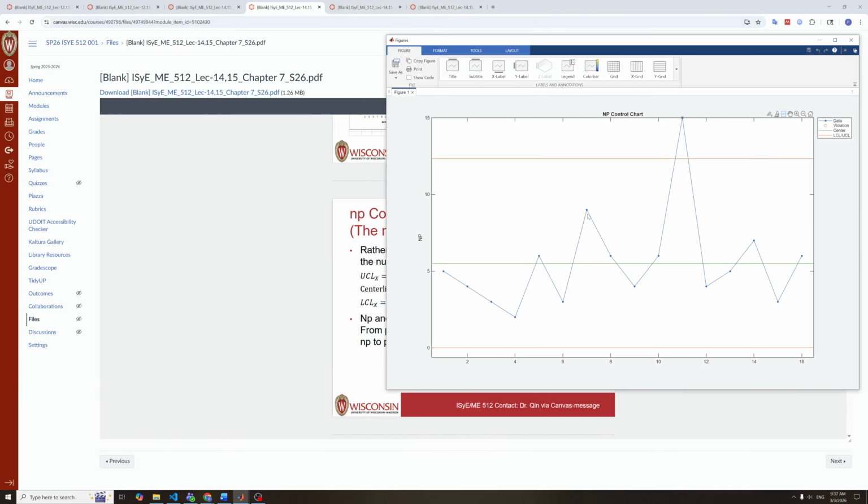From the figure, we observe 1 point exceeding the upper control limit. This point is marked as a violation and indicates special cause variation, that this sample has an unusually high number of defectives compared to what would be expected under binomial variation. Therefore, the process is not fully in statistical control, and that sample should be investigated.